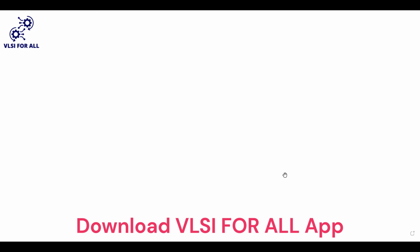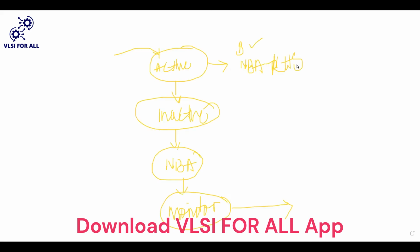From this we can tell that as the $display is in the active region, whatever the value of A is, and also whatever the $display statements are there, that is taken care of by the active region. Whatever the $write statements are there, those will also be taken care of by the active region. And in the inactive region, we are going to consider whatever the #0 statements are there. If we are giving any #0 assignment before a statement, then that type of statement will be executed inside the inactive region.